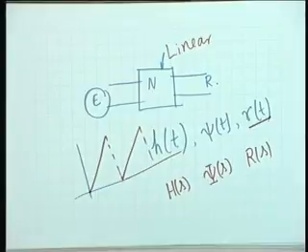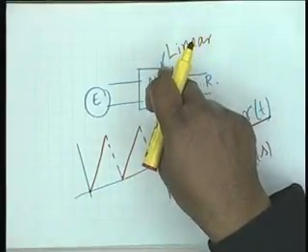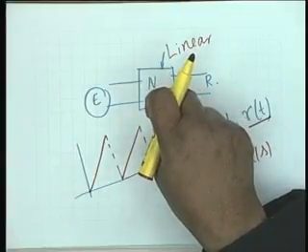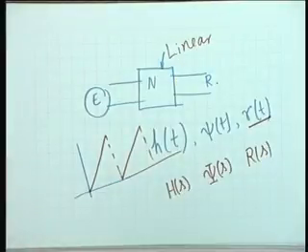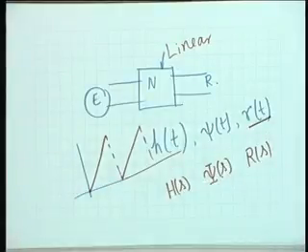But one should remember that in such frequency domain descriptions, if you want to take the Laplace transform of h of t to find h of s, the network initially should be relaxed. That is, there should be no initial energy storage in the network. The capacitors should all be with 0 charge, the inductors should all be with 0 initial current. It is only then that such gross descriptions suffice, and this shall be one of our conditions.